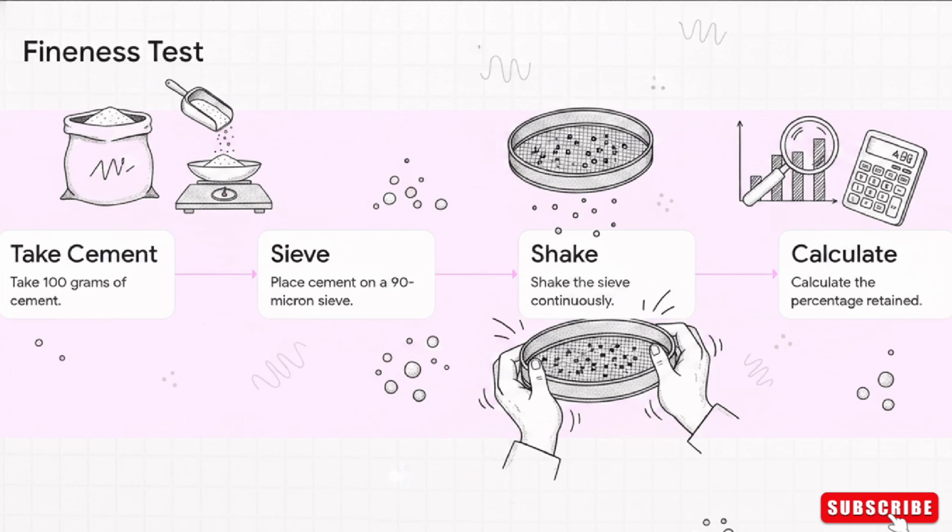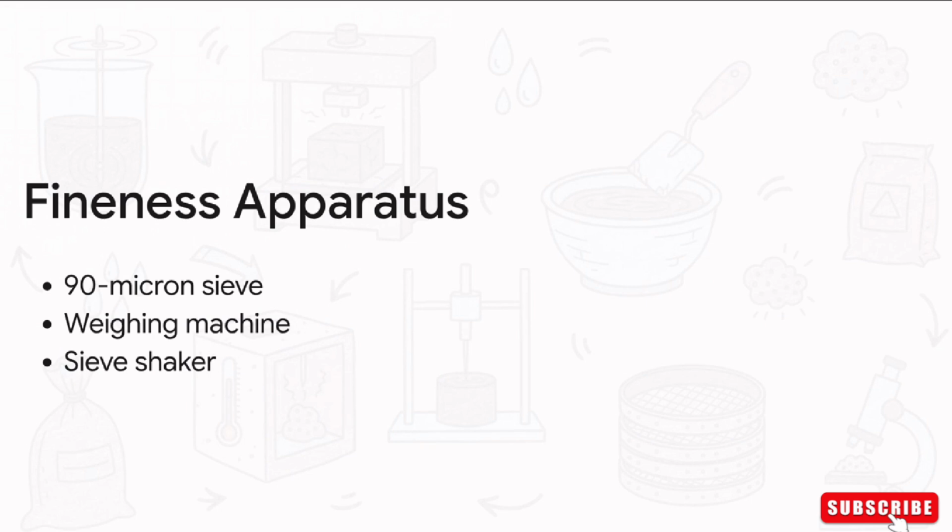To actually test this, we take exactly 100 grams of cement and place it onto a highly precise 90-micron sieve. We shake that sieve continuously, and then calculate the exact percentage of cement that gets retained right there on the mesh. Take a look at the high-definition precision of the tools we're using here. We've got the 90-micron sieve, a highly calibrated weighing machine, and that mechanical sieve shaker.